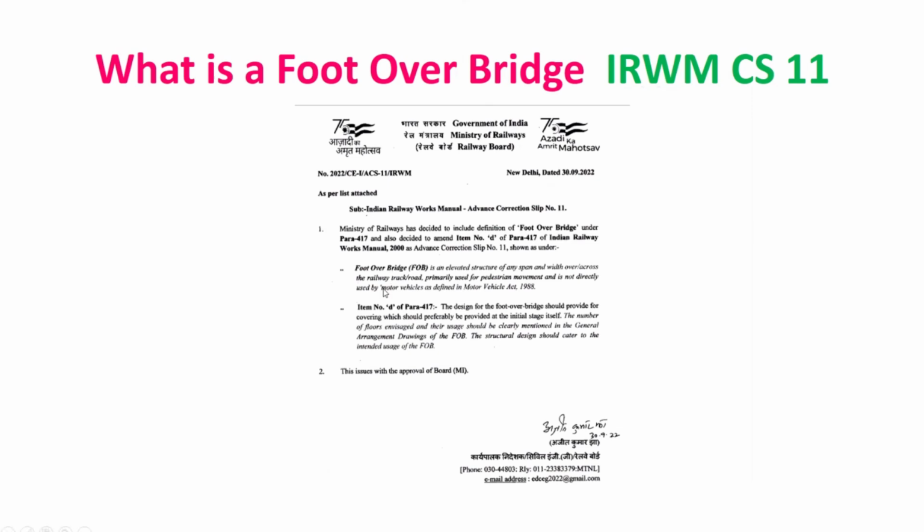Why I am sharing all this information is that the electrical people may say that I have to place the transformer here, install it there, put it in the building complex. You may not be aware of what the provisions are. Then where do I build the wall, how far away do I build it? So I have given clarity on what to do if there are two side walls, and what to do if there are three side walls. In case I have to enclose all four sides from a security point of view with a door, then it has to be 1.25 meters.